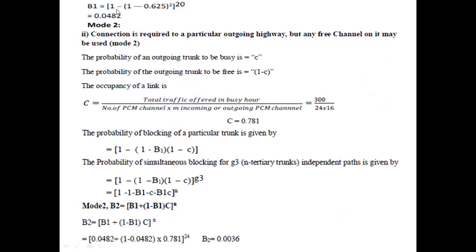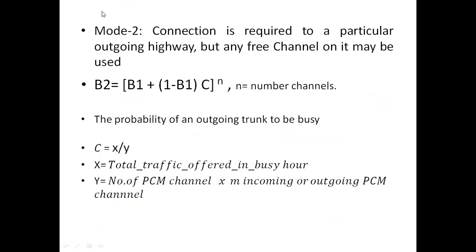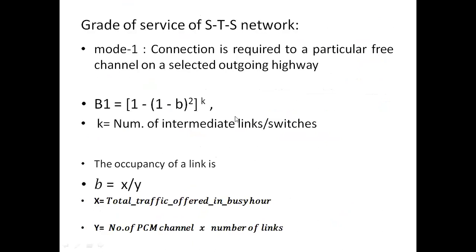B1 can be calculated by substituting the small b value in the B1 equation, to the power of 20, which results in 0.0482. This is a dimensionless quantity, which is the grade of service. You already know the equation for the STS switch. The grade of service for mode 1 is given by this equation.